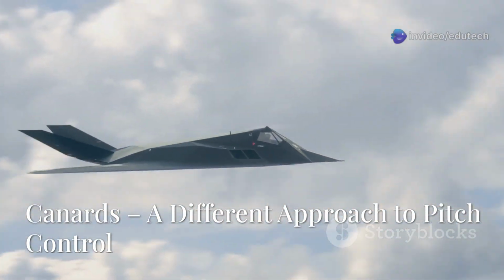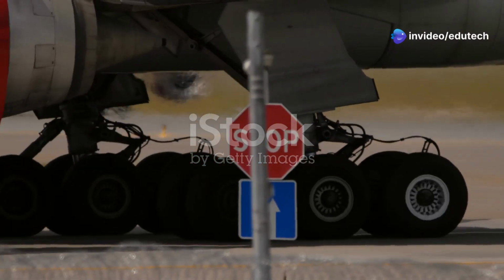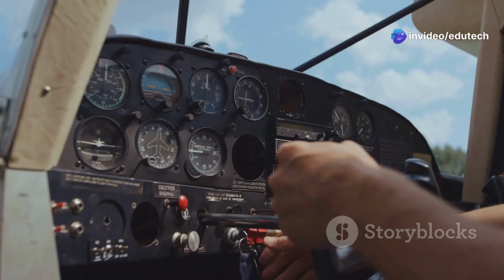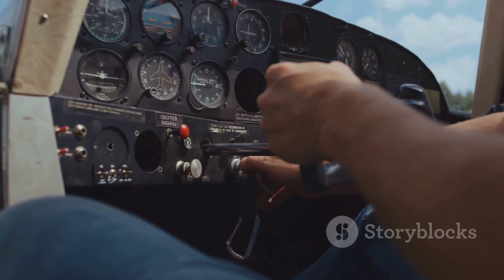A canard utilizes the concept of two lifting surfaces. It functions as a horizontal stabilizer located in front of the main wings. In effect, the canard is an airfoil, kind of similar to the horizontal surface on a conventional aft tail design. But the difference is that the canard actually creates lift and holds the nose up, as opposed to the aft tail design, which exerts downward force on the tail to prevent the nose from rotating downward.